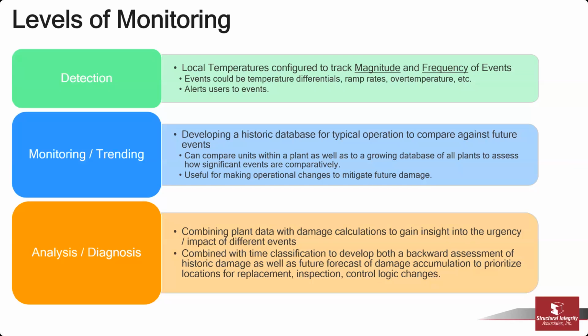In one of the later presentations, Wes will get into some systems that we've been monitoring that look good on first pass, but if you look at their historic trend, there'll be an increase in temperature differentials versus time, and if you dig into it, it's often because valves are slowly leaking by more and more, or the amount of spray has been increasing on attemperators, or there's leak-by around baffles, and tubes are heating up higher on the sides of the HRSG.